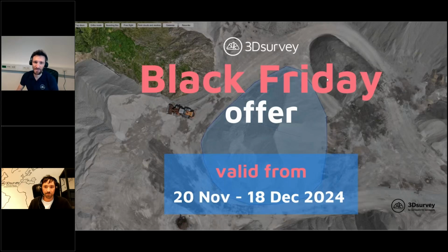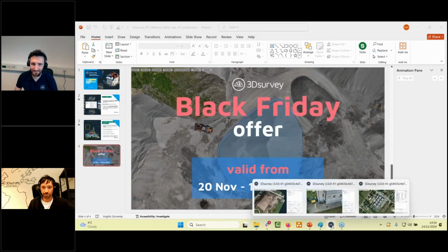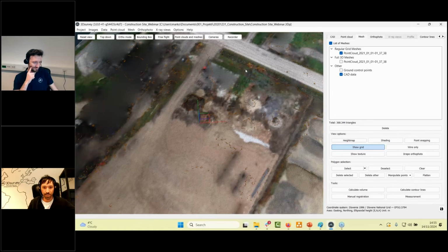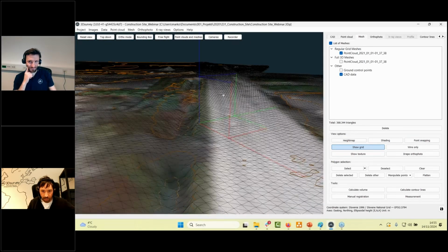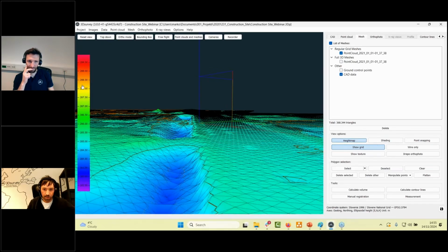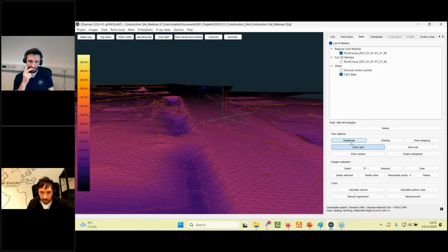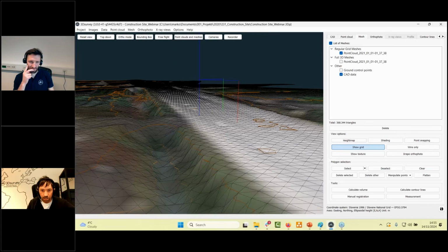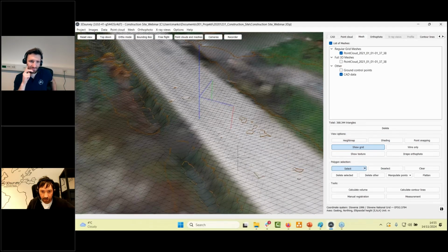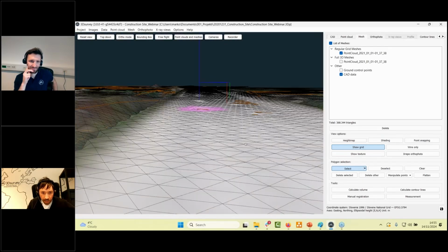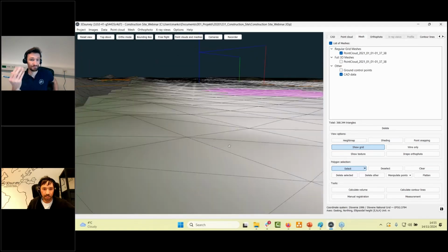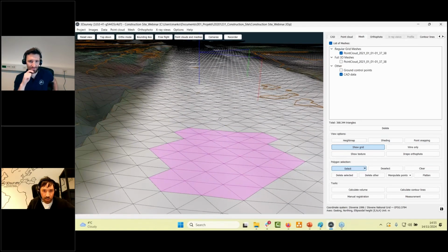So Arthur has a question. Any way to smooth a wall or road so as not to have a varying surface? So the problem where you get a road that's not smooth. What can we do there? Yes. If you are talking about the DSM level, this is super easy. Let me check what kind of road we have here. Maybe you can see some holes here in the road. So there are a number of options. One is just selecting the area around the uneven terrain and clicking flatten. In this way you can correct uneven terrain point by point.